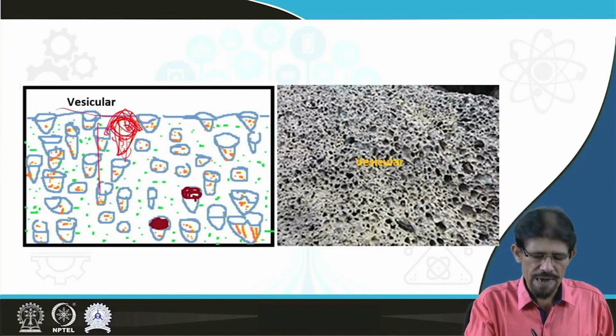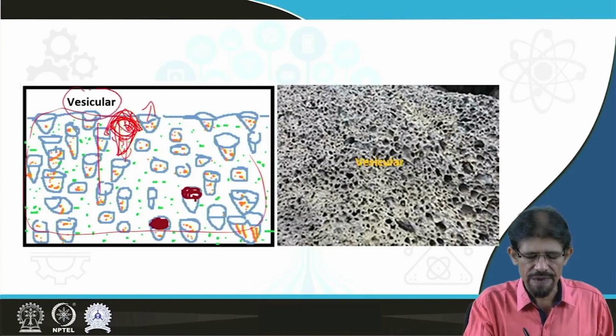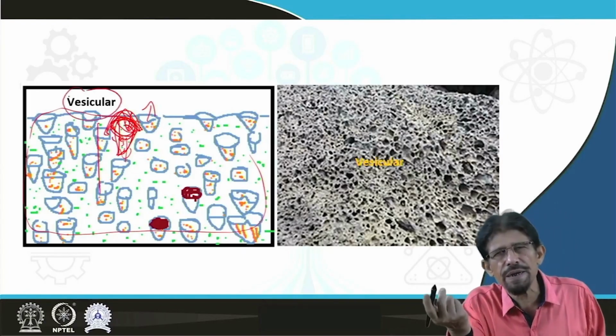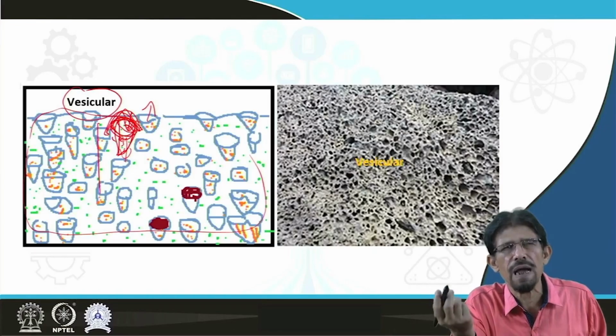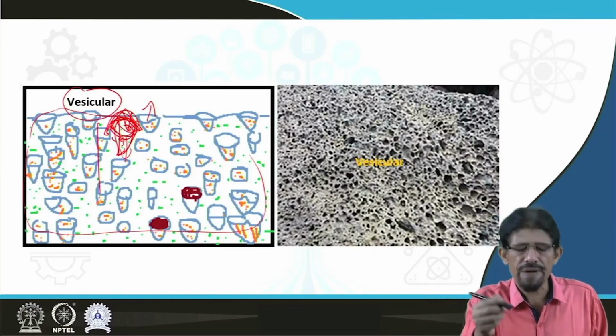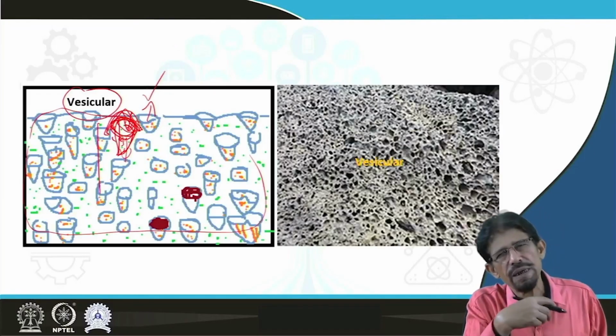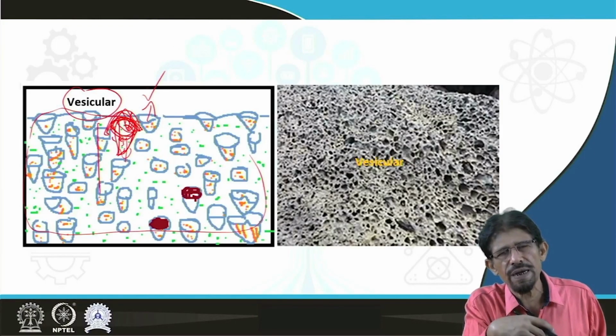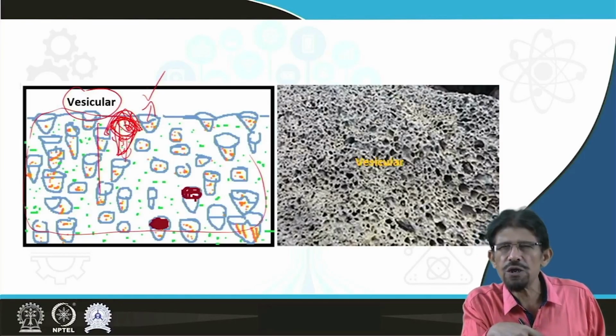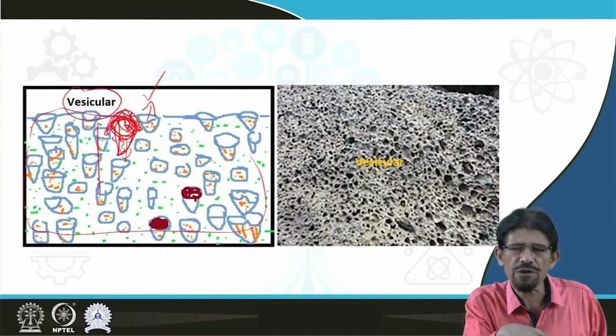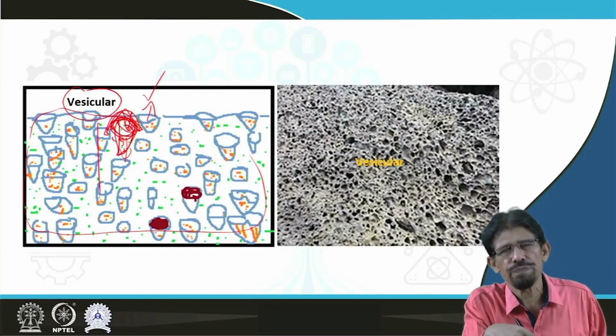In geology, if these vesicles are filled by secondary minerals, then we recognize it as amygdaloidal type. But for our engineering purpose, we are going to consider these as vesicular ground. It is filled by secondary material or loose weathered material. It is saturated, fully, partially or dry in nature. So all these conditions are going to affect the level of preparation and treatment.